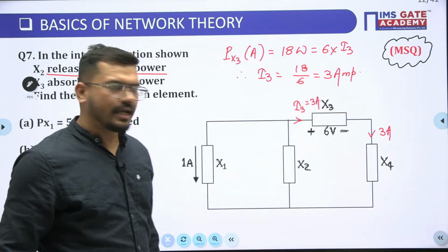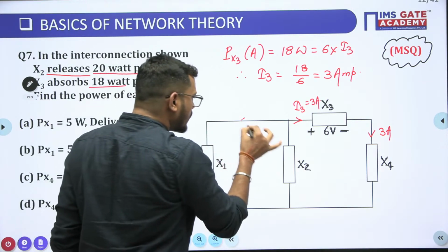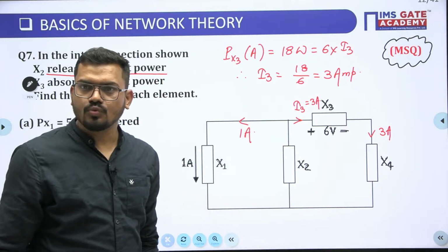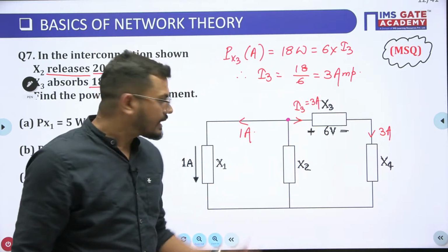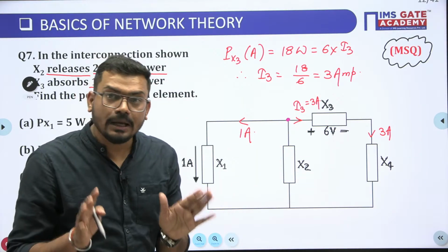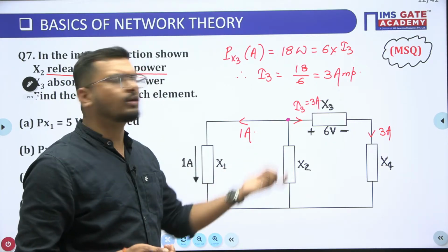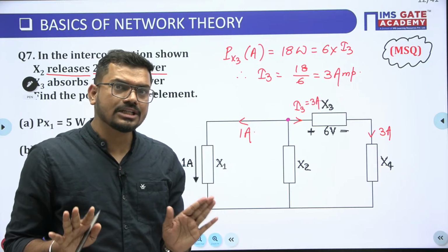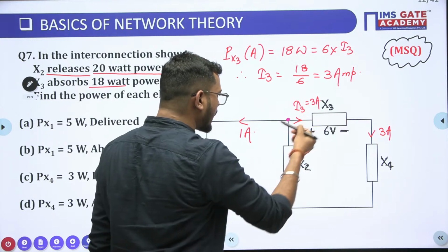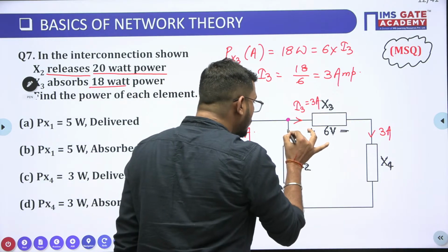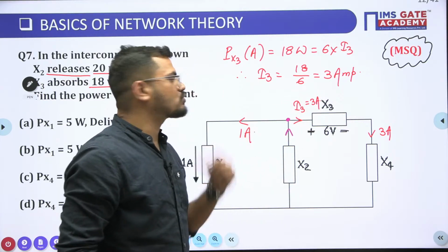Very good. Okay. Now as it is given in this diagram, this current is 1 ampere. So can I apply KCL at this node, guys? Yes or no? We can simply say KCL. It is not nodal analysis, we just have to apply KCL here. Is it okay? Respond, please. Now if we apply KCL here, this is the outgoing current, and this is the outgoing current. So there should be an incoming current of value I3 plus 1, which is what, guys?